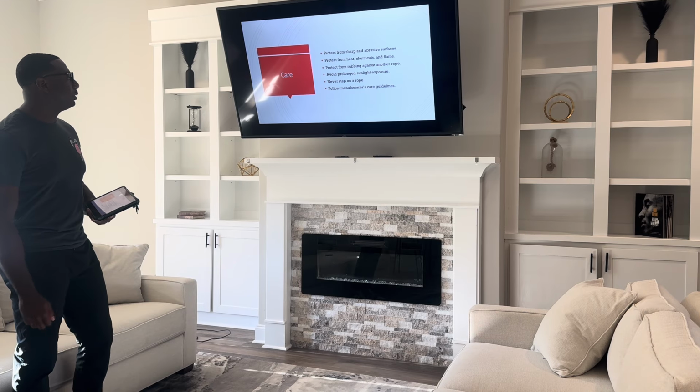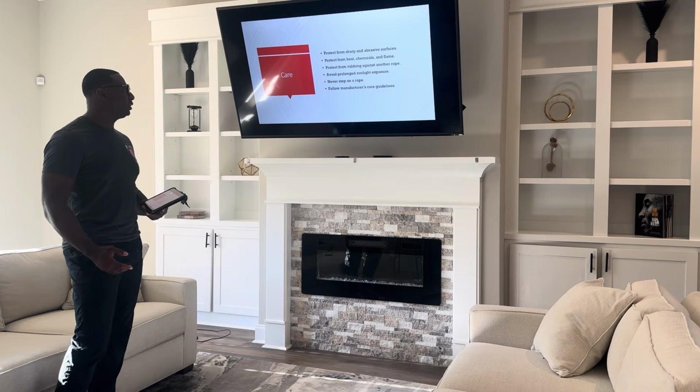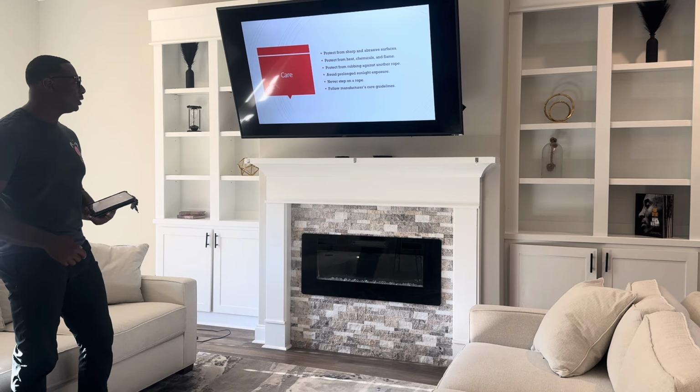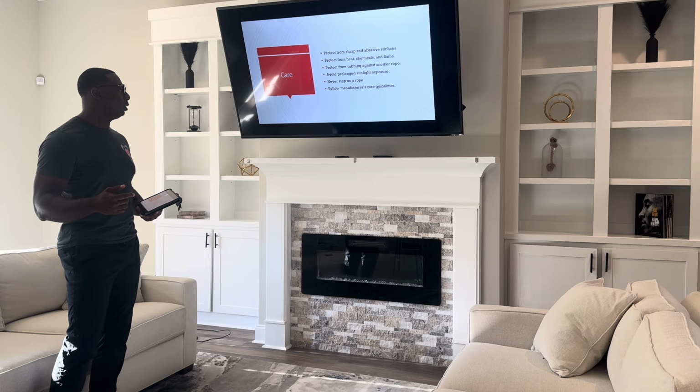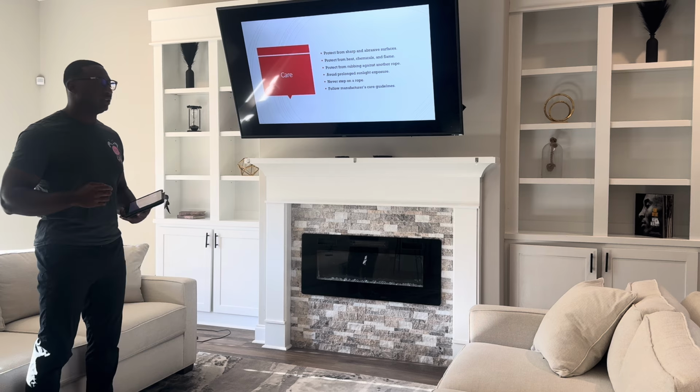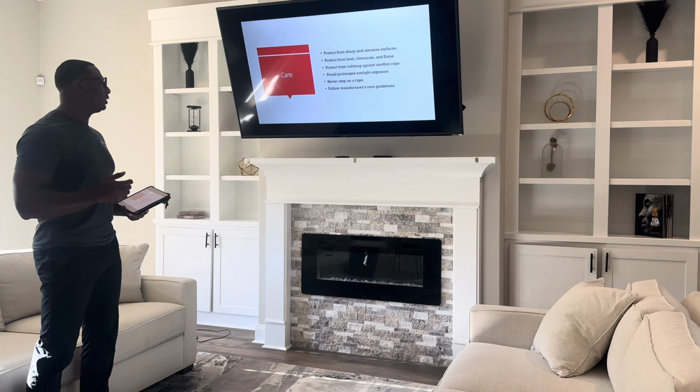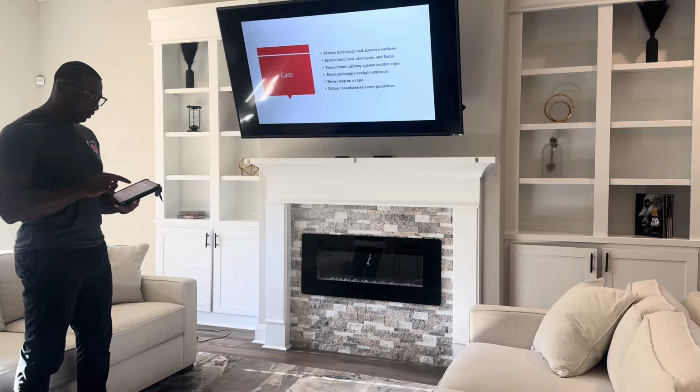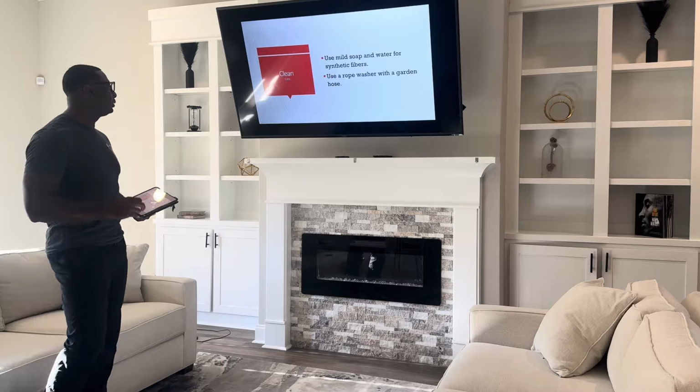When you care for rope, you want to protect it from sharp abrasions, protect it from heat, chemicals, and flames, protect it from rubbing against other ropes, avoid prolonged sunlight exposure, never step on the rope, and follow the manufacturer's care guidelines.